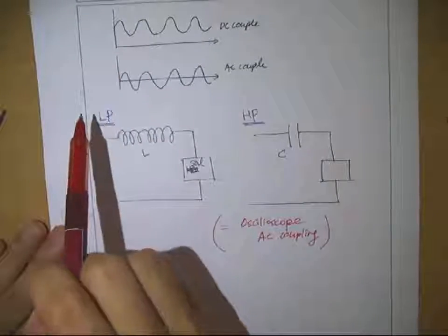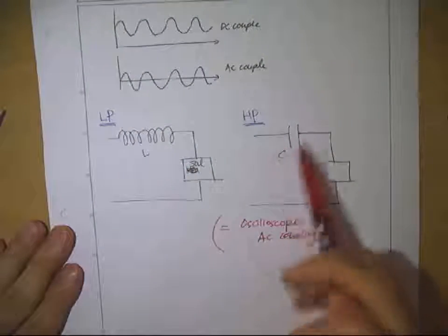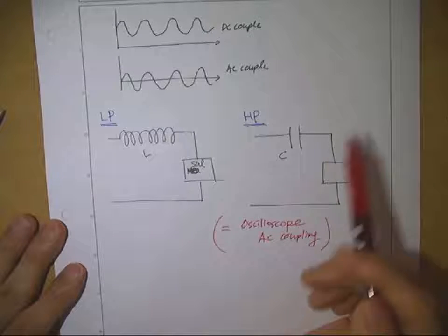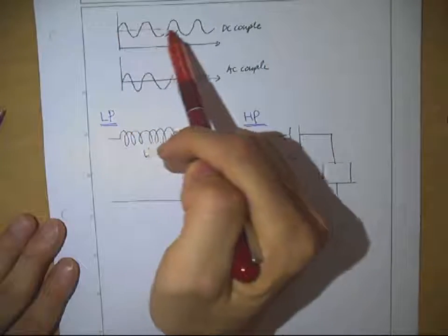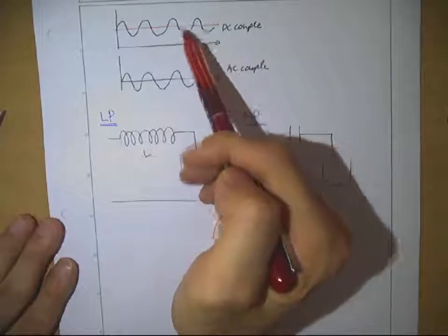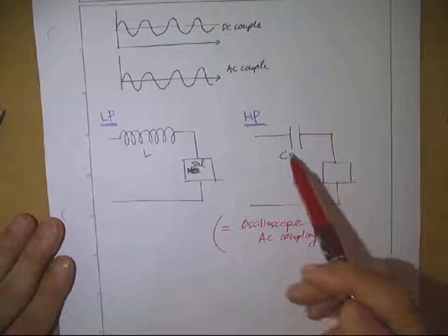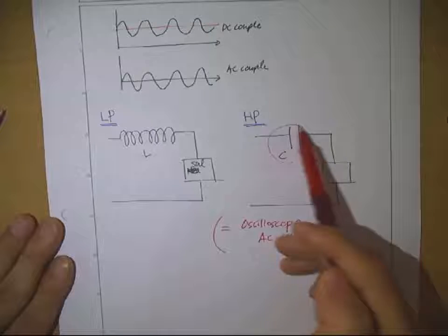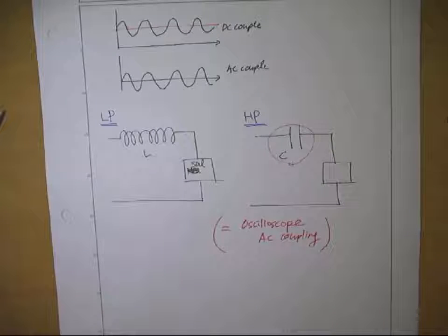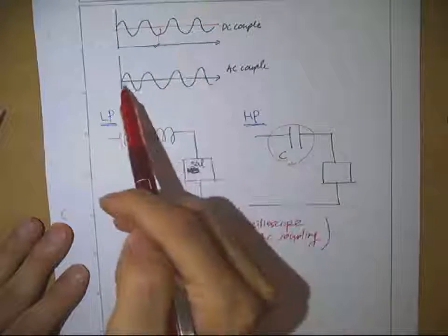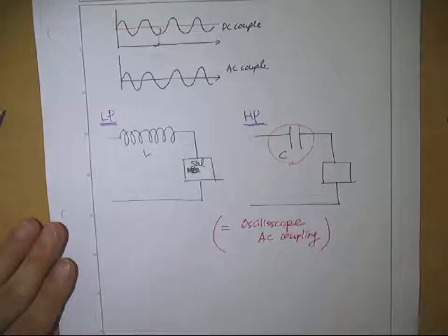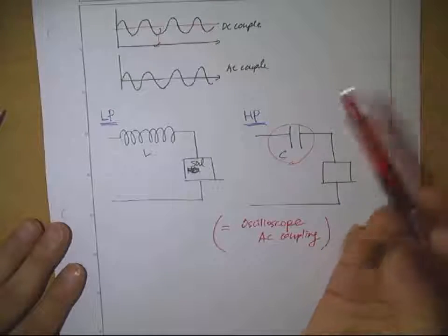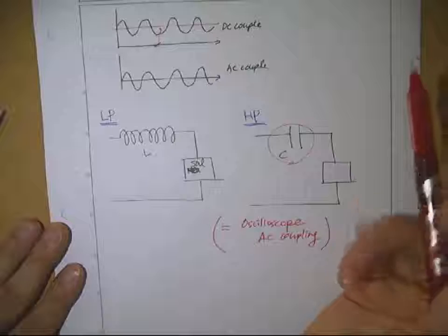So, for example, when you don't apply this capacitor in the circuit, then in the normal case you are just doing the DC couple. Then you have a DC offset and also the real signal, the oscillating part here. Then as soon as you add this capacitor in the circuit, you're losing the low frequency term. So this will go to 0 so that you have a well balanced signal, but you're eliminating the DC component here. AC couple case and DC couple case.